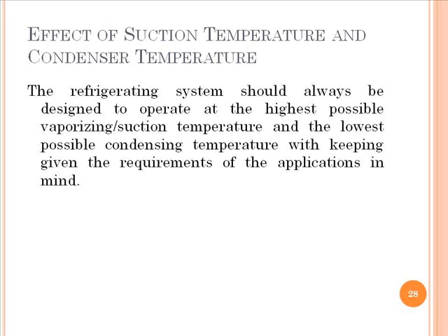The effect of suction temperature and condenser temperature. The refrigeration system should always be designed to operate at the highest possible suction temperature and the lowest possible condensing temperature, keeping in mind the requirement of the application.